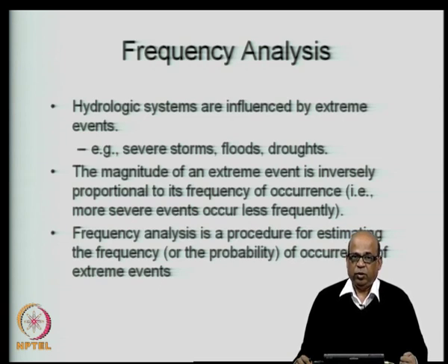This magnitude will be smaller than a flood event that occurs once in about 100 years. So, as the frequency increases, the magnitude decreases. Once in 10 years is a higher frequency compared to once in 100 years, and therefore, the flood magnitude that may occur once in about 10 years will be smaller than the flood magnitude that may occur once in about 100 years. With this information in place, we carry out what is called the frequency analysis.